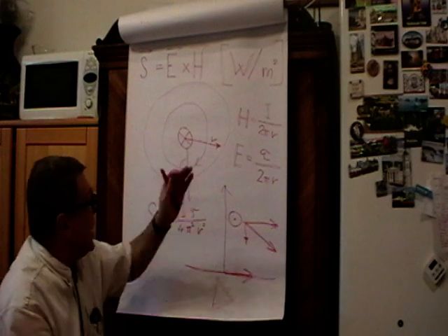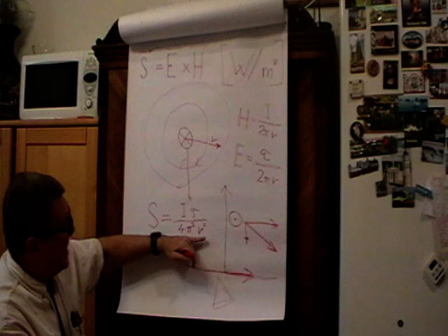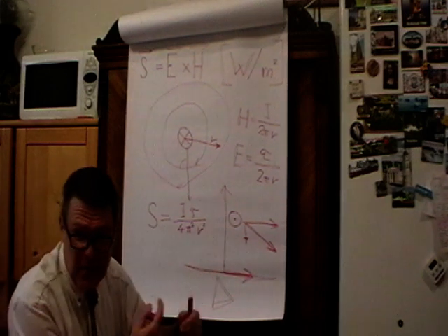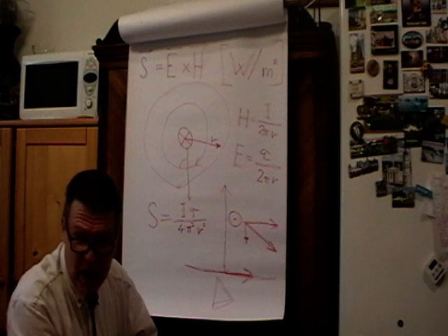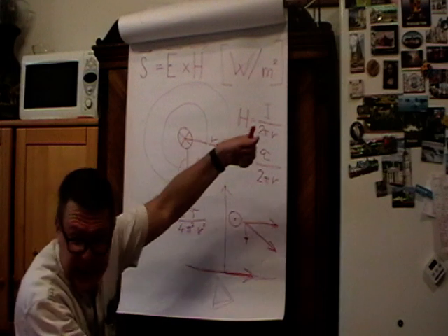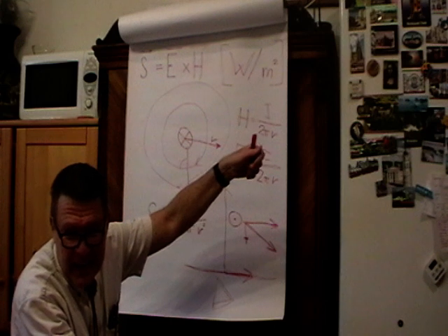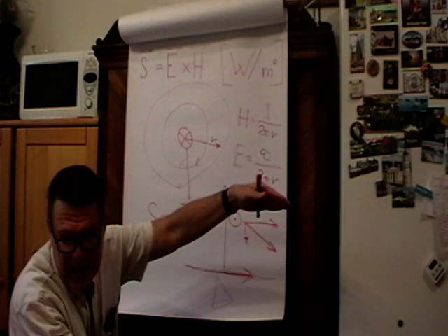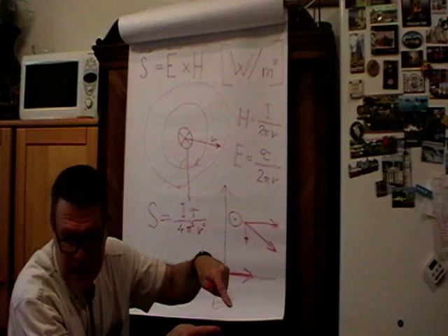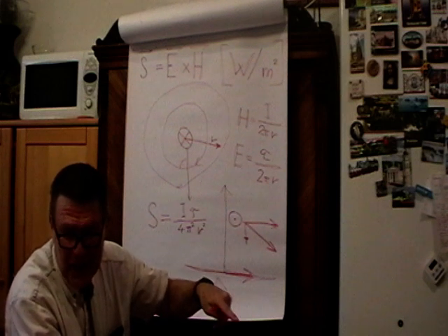There is the energy given by this, the energy density or the power density is given by this equation. So it's inversely proportional to the square of the distance. But it's sitting around the conductor and it's propagating along the conductor. But as the conductor is lossy, a part of that energy is propagating into that conductor, and this energy covers heat losses of the energy transmission,